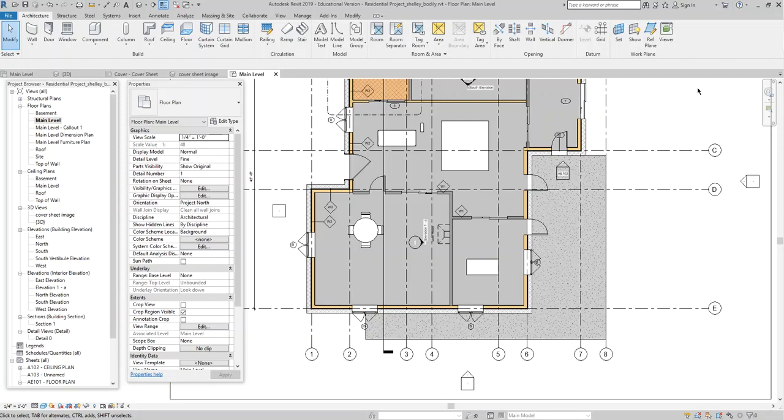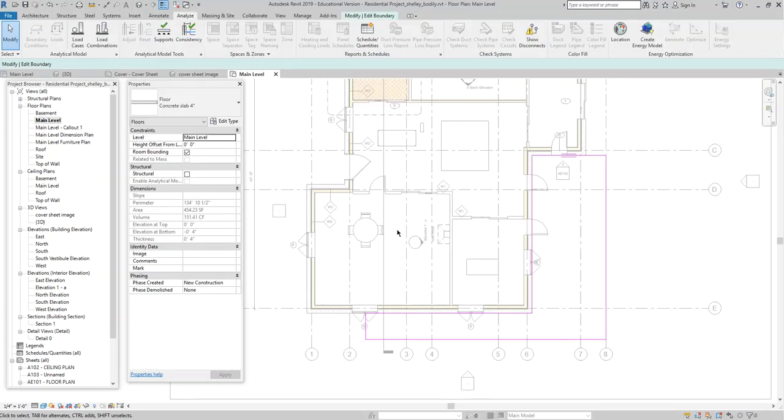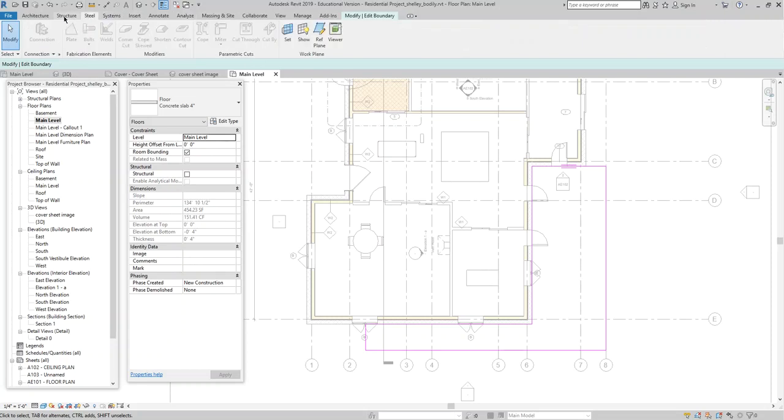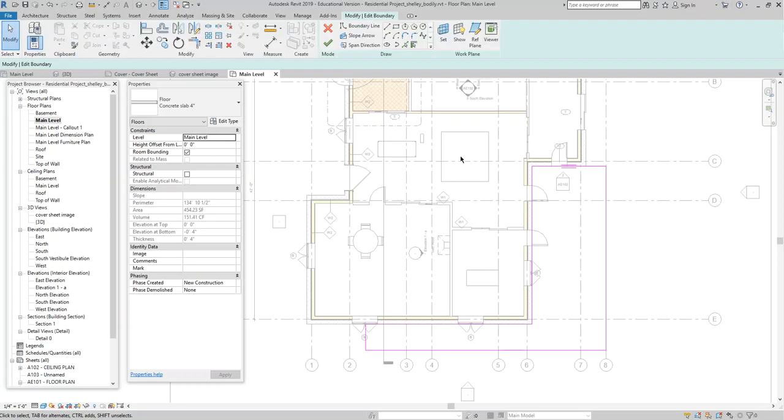That's another common thing. So Gabriel was trying to sketch. I'm going to show you guys this. He was trying to sketch, and all of a sudden he was like, wait a minute, I'm in sketch mode, but I've lost my tools, right? Where did they go? This is something that happens. You can go to other tabs while you're in sketch mode, but they don't do you a whole lot of good. Most of the stuff is grayed out, right? You can accidentally go to another tab. If you ever find yourself in sketch mode stuck, not being able to see your tools, just go back to this highlighted tab and you'll find them again.